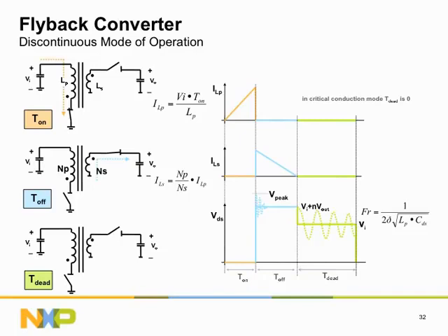The voltage waveform as shown in the lower graph is an idealized waveform. The actual waveform would only be such if the operation of the transformer, or better, set of coupled inductors, would be ideal. And in a practical situation with a real transformer, that is not possible, of course. With a real transformer, we will see some voltage ringing when the secondary stroke begins and after the secondary stroke ends.